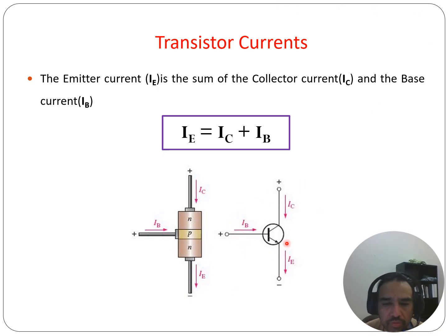There it is. So this is a schematic of a transistor. Specifically, this is an NPN transistor. So NPN, and the schematic symbol for an NPN looks like this. You see that little leg there with the arrow pointing out? That tells me that this is an NPN transistor. A good way to remember this is NPN, not pointing in.